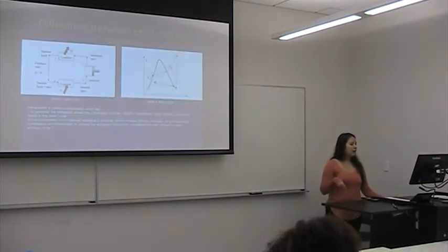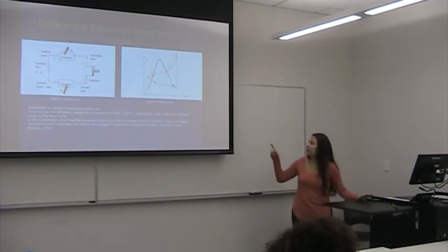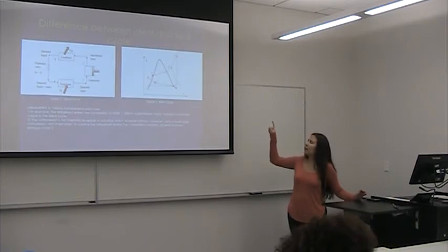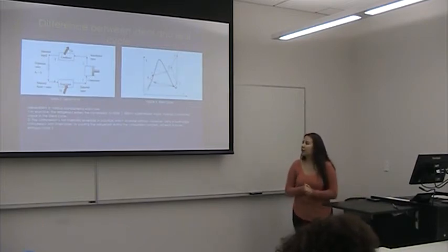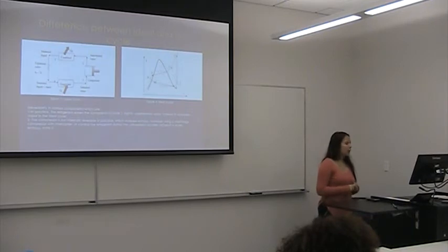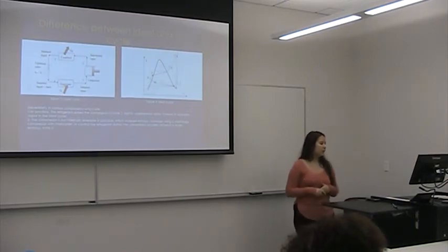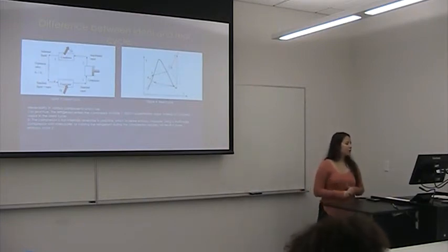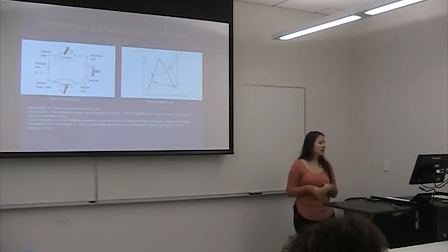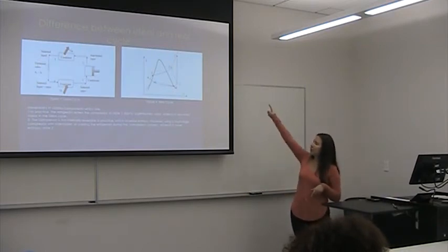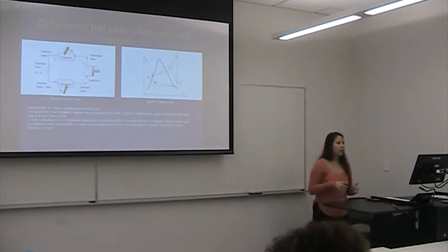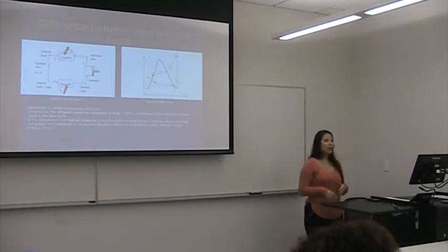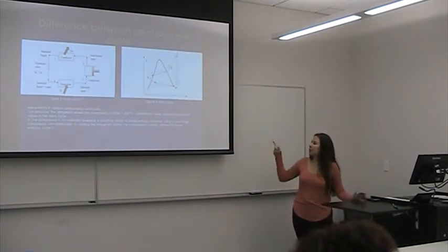What's the difference between an ideal and a real cycle? In figure number 4, the one in red is the ideal one, and the one in black is the real cycle. In practice, the refrigerant enters the compressor at state 1 as superheated vapor, instead of saturated vapor as in the ideal cycle. Also, the compressor is not internally reversible in practice, which makes the entropy increase at state 2. But in the ideal cycle, we can make this refrigerant cool down in the compression process, and that will result in a lower entropy at state 2.